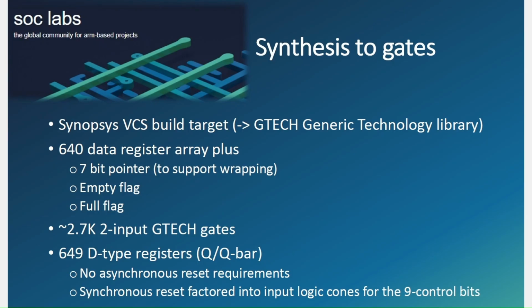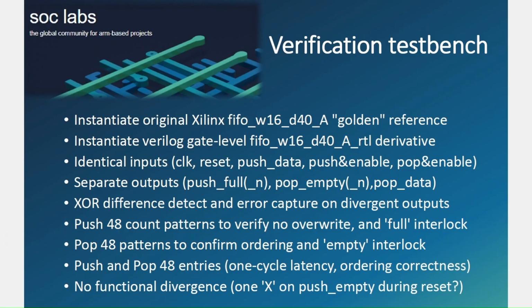The synthesis to gate level is done through Synopsys GTECH, generic technology library. It has 640 data register array plus a 7-bit pointer, empty flag, and full flag, and 649 D-type registers for output and output invert.